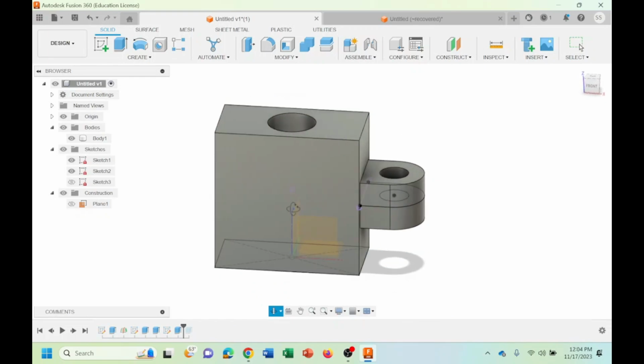This is another example that shows, in these two examples that we had in this video, I wanted to show you something similar to two-dimensional sketching, where we try to have everything constrained and define the relationship between the different objects using constraints. Here we follow the same mindset. So whenever you are extruding anything in 3D, just keep in mind, whenever you make a new object, try to use a constraint and show the relationship between the different objects that you have.